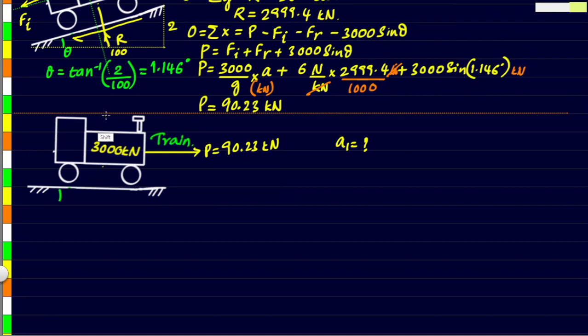Once again, let us take all the forces that are acting on this free body diagram. The downward weight will be acting downwards, then there is a normal reaction here, let's call it R1, and of course there is a friction force which is acting backwards. And finally, to bring it in equilibrium according to D'Alembert's law, we have to apply the inertia force in backward direction. So here we can go ahead by taking the reference planes as horizontal and vertical.